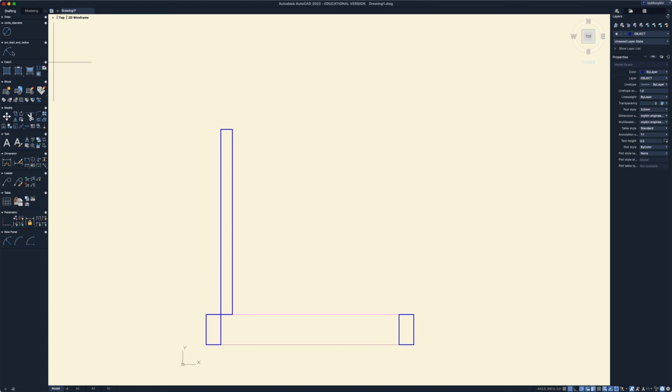Okay, now if I select that one, I'm going to start down in the bottom right at this point, and it swings up to that point with my radius being the length of the door, and that will form a perfect radius for you. So I'll do that again. I chose my arc at start end radius, start, end right there, and the radius, I could just type 610 in there, but it's just as easy to come down and touch this because I'm coming from that point down the length of the door, which is 610.